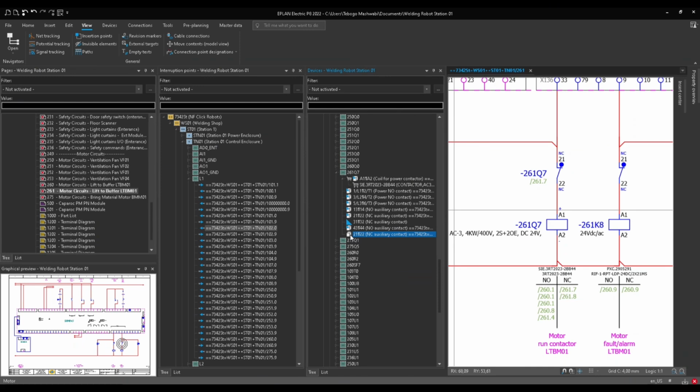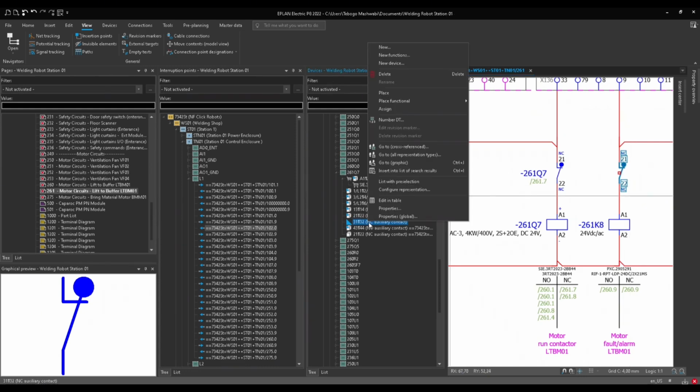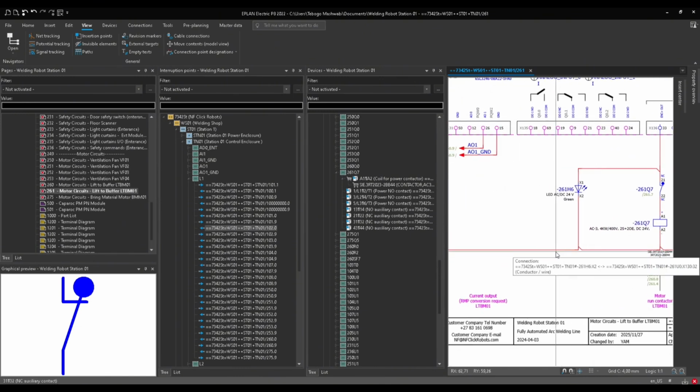So now what we need to do is, in EPLAN, say, okay, let's not make this one a 21 and a 22. We can click on this one and say assign, and assign it as 31 and 32. And therefore you can see all of them are with the triangle and the cube matching each other. But now we no longer have anything to use on this device.